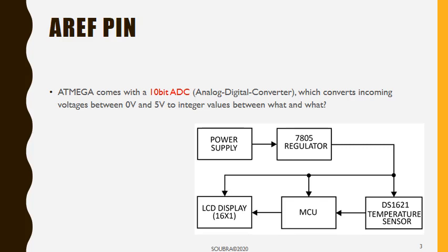0 and 1024. Not bad, but someone can do better. Yeah. Come again? So between 0 and 1023. How come? Yes. Good. So definitely you dispose of 1024 numbers to represent 0 to 5 volts. However, if we put the 0 aside, we're left with 1023. Make sense? Perfect. So it's between 0 and all the way up to 1023.